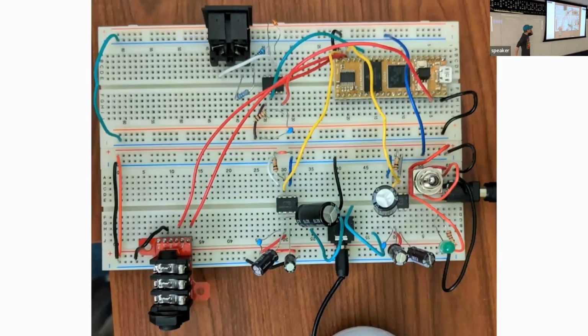This is what the synthesizer looks like from that flow diagram. Again, the flow starts up with that black connector over there, and that goes through that teal wire into the Daisy, which is where the MIDI is going in. And then audio is coming out at two tabs, a left and a right channel, and these red wires are going out at a certain line level, so you can plug this into a guitar pedal or anything that accepts a line level.